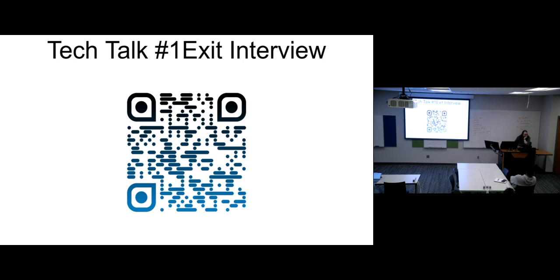I had a question about the Kalman filter because you just mentioned that it's kind of close to PID controllers, right? It's adjacent to it. It is not quite the same concept, but it would be the next step. Whatever you produce as a solution out of your navigational filter, Kalman or otherwise, would then become a set point to a PID controller.